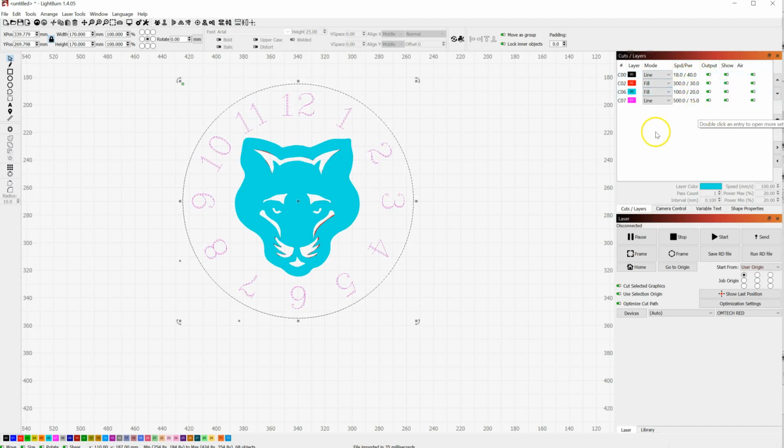This is my home laser, so the one at school is going to be different. And then I have this etching very quickly, at 500 millimeters a second at 15%. So it's going to be kind of a light burn. Again, the one at school is going to be different. And we can confirm everything looks right.